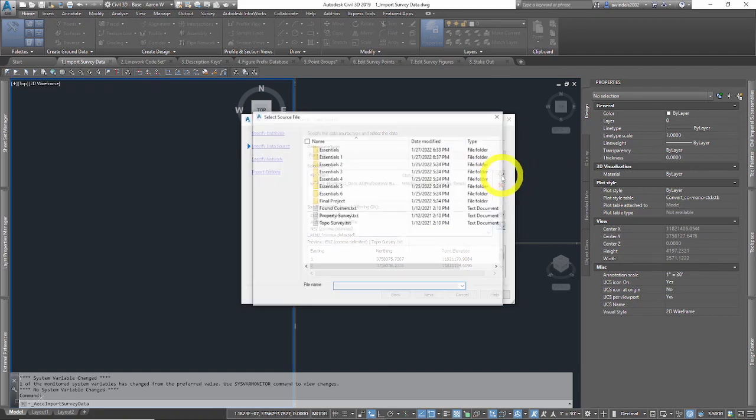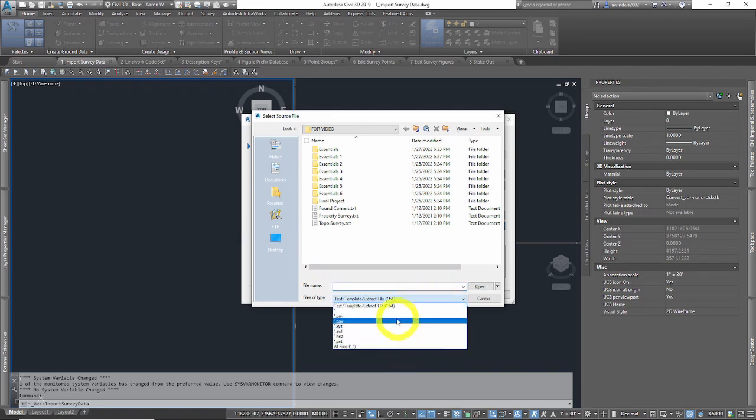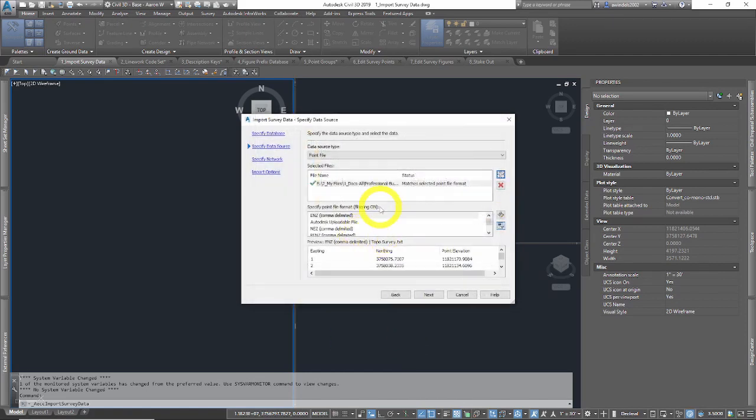Now we hit plus here again. There's a few different types of survey data sources, which is also on page 42. Most commonly, people use CSVs, XYZs, or text files for simplified point files, sometimes land.xmls, but in this case we're using the TXT, simple ASCII file.